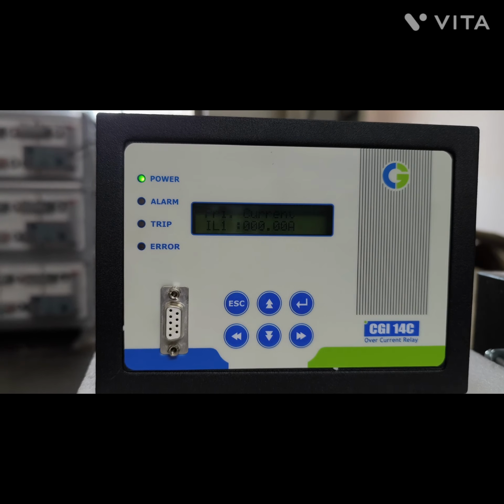Actually we have to give the same password, 002. So here the protection is there, and I can change it. Here you can see 3 phase to phase and NDR. This is the neutral displacement. If not required, only 3 phase to phase will be there like this. So 3 protections, phase to phase only voltage protection.